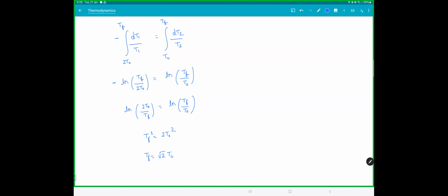Can I say like this? The heat lost by the source and heat gained by the sink, what happened to the remaining energy? That is the work done, isn't it? The balance. Let's say if source lost 100 and the sink gained 40, what happened to the remaining 60? So work done must be heat lost by source minus heat gained by sink.